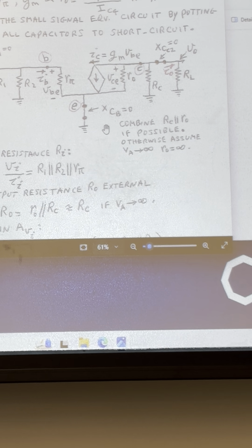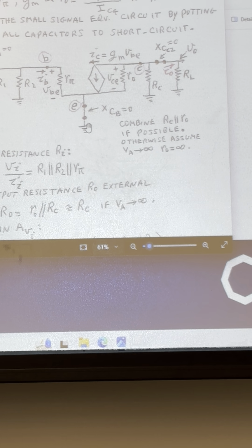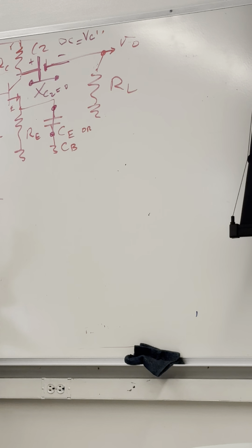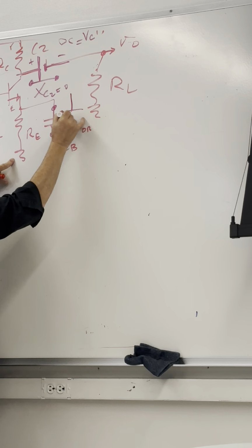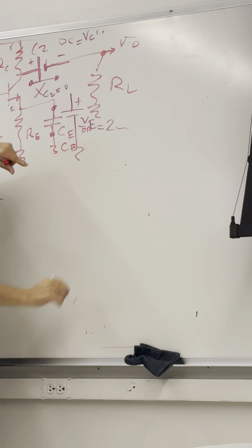And this one, which is the big question in here. What happened to RE? We have an RE there, but why doesn't it show? Because this is shorting the RE. So it doesn't let RE carry any signal. No signal whatsoever on RE. But you know what you have? Here you have like that 2-volt battery. You remember the VE equal to 2 volt? It's in.